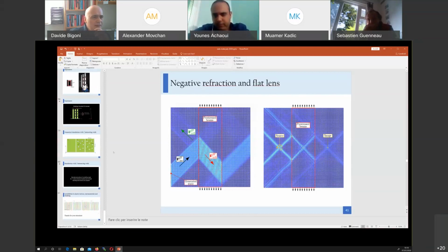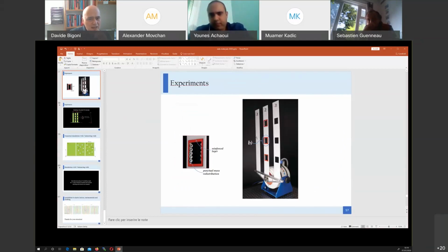So the message is that if we take these three structures, the first two, 1 and 2, have the same eigenmodes up to the 7th or 15th eigenmode, and so we are prone to believe that they behave as the same thing, because these are the free vibrations, the resonant modes, and so they coincide in the first, in the second, in the third, in the fourth, and so on.